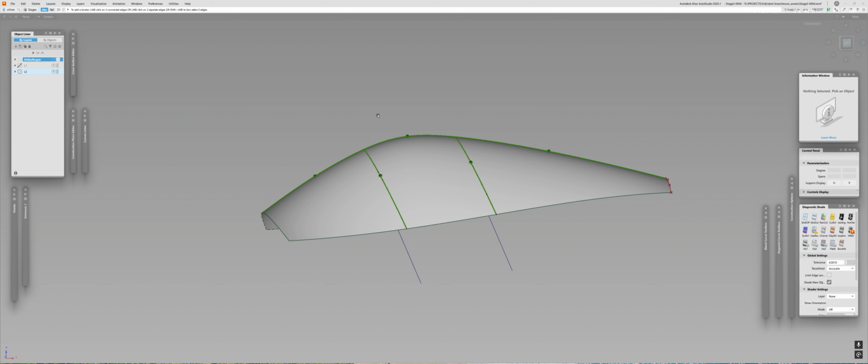Now, you can just randomly place some curves, and then through a lot of heavy modifications of the surfaces, basically manual CV massaging by kilometer, just slowly but surely eliminating the errors. But it's a very, very long process and doesn't really make a lot of sense. So use the power of Alias and use your curve networks to create the proper flow.